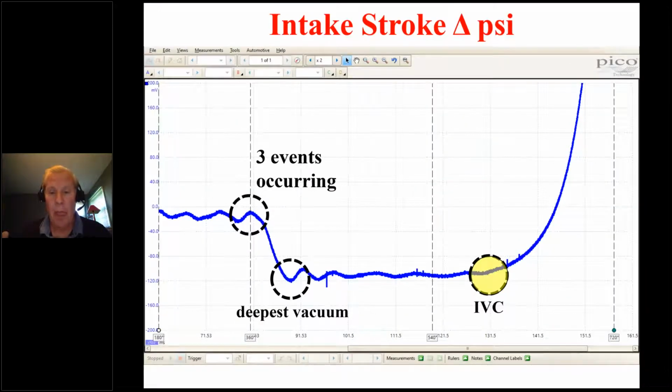So finally, as we move to the compression stroke, so I talked about the complexity of what's happening here. This is a good reference, 30 to 60 degrees after top dead center, and now we come to intake valve closing. And of the 4 valve events, this is one of the most critical for being able to build pressure once again in the cylinder.